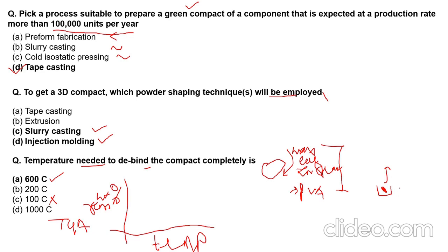As it is heated, the material goes through various changes, mass losses because of evaporation and because of reactions, oxidation and reduction reactions. That change in mass is reported in the thermogravimetric analysis, so based on temperature we have a curve of weight remaining. With increase in temperature, the weight remaining decreases, obviously, because the material is melting, evaporating, and getting removed.